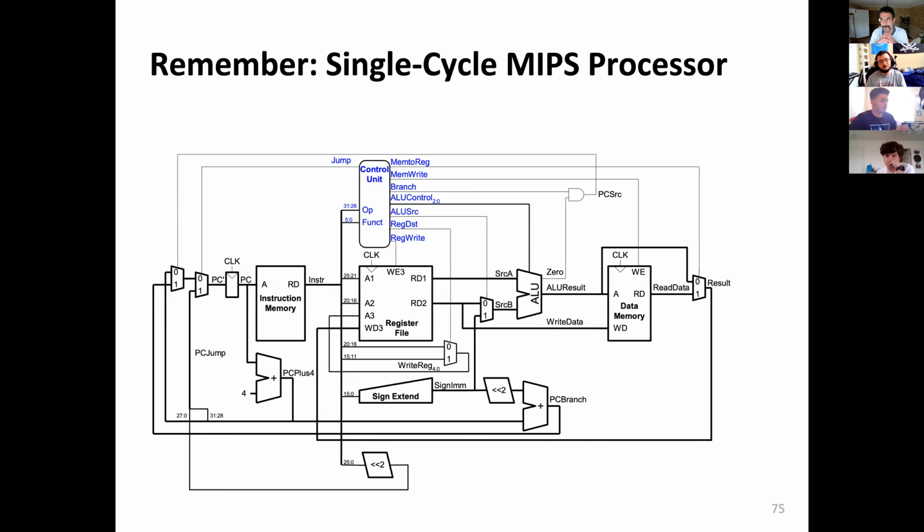The thing that I wanted to hear more clearly is about this property that I mentioned, transitioning between AS to AS prime. As Bella mentioned, in single cycle, we do not need it. Or more clearly, related to the exact question I asked, we could add it and nothing could go wrong in terms of this property. We could technically add this flip-flop in between and nothing will go wrong. But as Bella mentioned, it adds to the time it takes to execute the instruction, because writing to a flip-flop takes time. It's not zero time. So we are adding some artificial time which is not really needed.